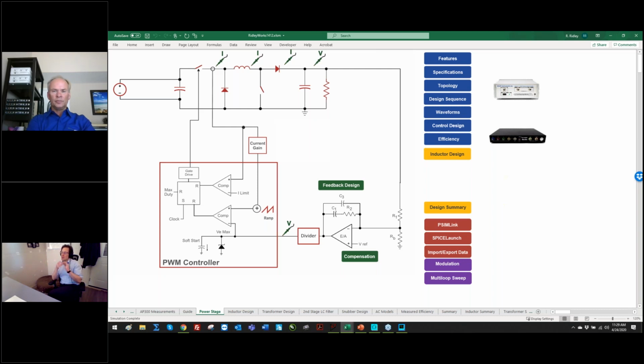There's another one that Ray doesn't like, which is a copy of what Simplis does as well. It's called the multi-tone or multi-sine, where you inject a bunch of frequencies in one cycle. That one can do a little bit better in unstable systems because you're limiting the damage to one cycle.